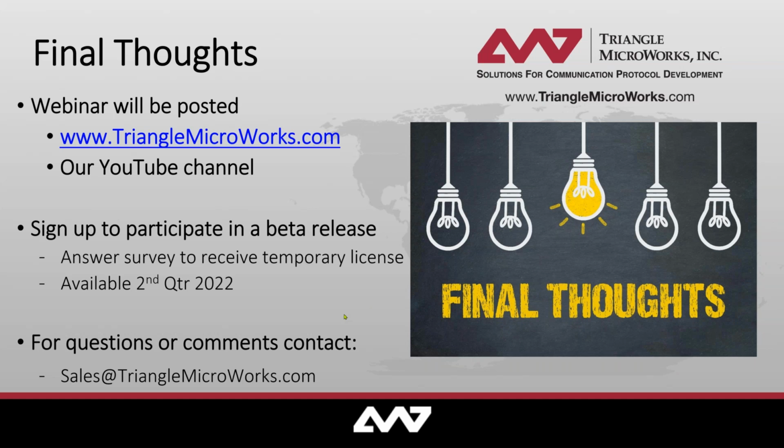But again, if you want to simulate an SCL device in a gateway, and all you're looking for is protocol traffic, I want to change this attribute in the device and see it go through, we simulate SCL models all the time. Again, the clear point is, when we say simulate here, we're simulating the model and the protocol, but not necessarily the behavior. So if you wanted to plug an SCL device into your substation simulation and have it behave the way an SCL device would in the field, you would have to program the desired behavior into DTM using either JavaScript, or in future versions, we're going to use 61.131 to program behavior of devices.